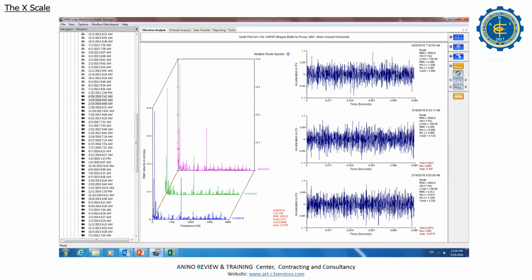You can train the spectrum, and also the G's, the acceleration. It's good, right? If you do analysis, you can predict that maybe next month vibration will go high. This is February, March, then April. Every month I get the reading. That's our job, to monitor.